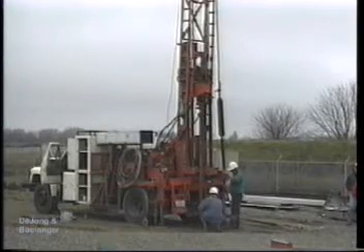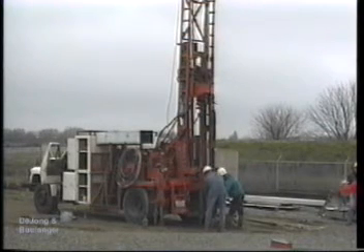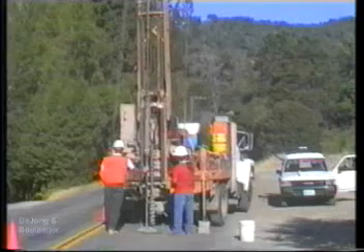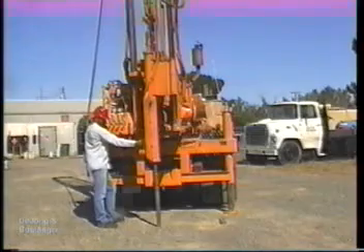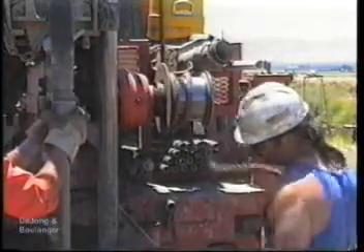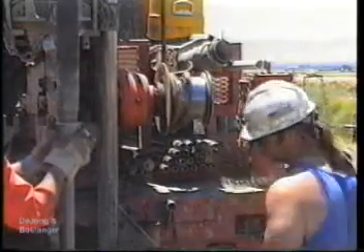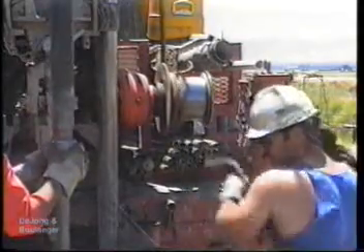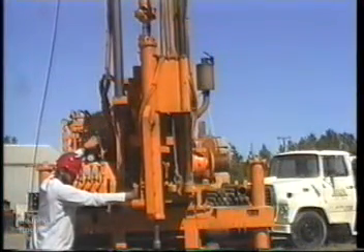For sampling, the split spoon is attached to a series of drill rods and lowered to the bottom of the borehole. The top drill rod is fastened to a hammer which drives the sampler into the soil. Of the many types of hammers, the most common are variations on the drop hammer, which is manually operated, and the mechanical trip hammer. The driller lifts the drop hammer by pulling on a rope that is looped around a rotating drum, or cathead. By pulling the rope, the operator uses the friction between the rope and the cathead to pull the hammer up. The hammer is dropped by releasing the rope, thus reducing friction between the rope and the cathead. The trip hammer performs the same function, only mechanically.